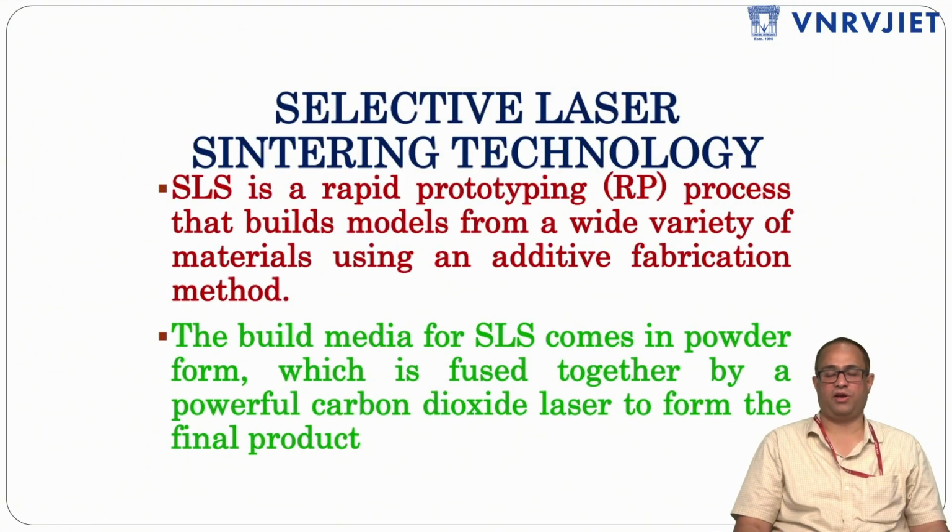Coming to the next technique, selective laser sintering. This comes under powder-based additive manufacturing. Here also, no additional supports are required, because the powder left over after sintering acts as the support. So only this process and the previous process do not require support structures.